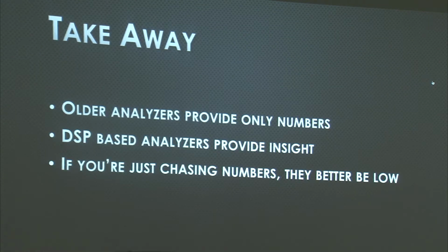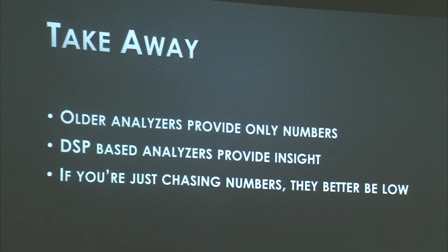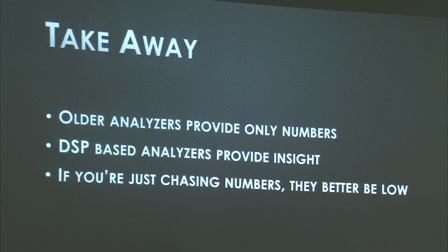Crossover distortion is actually very audible at lower levels, and this is a fairly high level, but it's still audible. If you were just looking at the measurement of THD plus N, you would see 7% on all of those. Now, if you look at the second harmonic, the third harmonic, both of those would show a 7% THD. The other ones would show almost no THD because the extra content wasn't harmonically related.